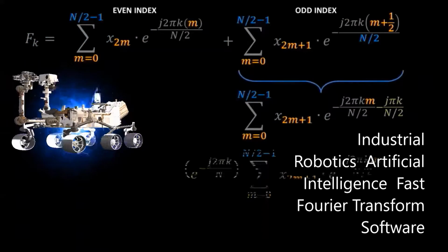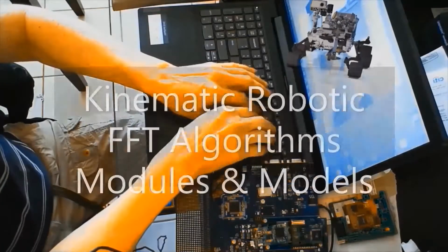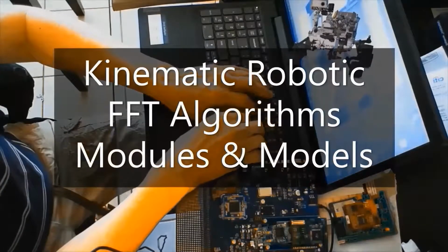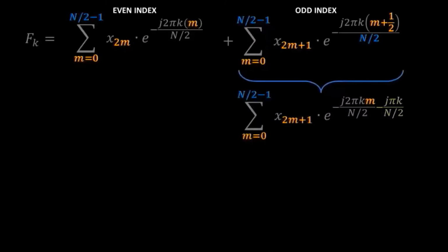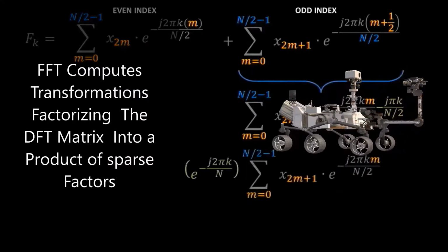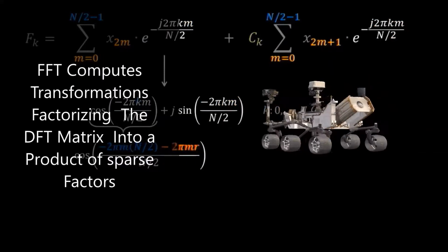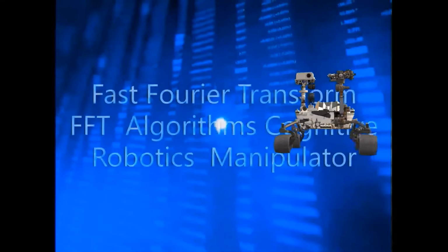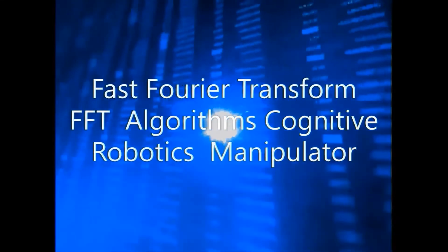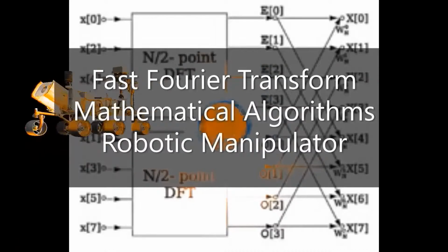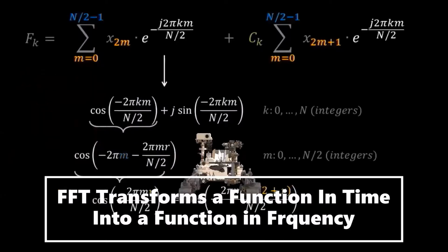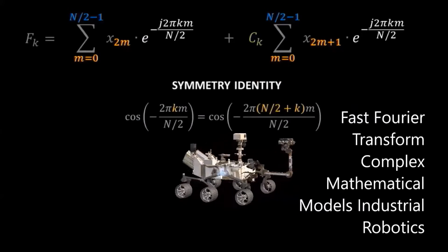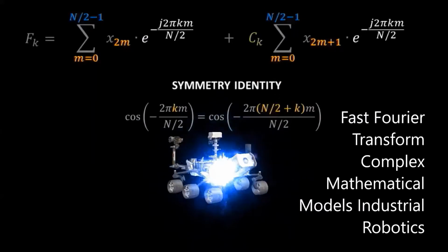The computational requirement of an FFT, fast Fourier transform, is given by the equation N c MULT-FFT is equal to n log 2 n over 2. Secondly, the number of complex multiplications and additions must be translated into real operations.